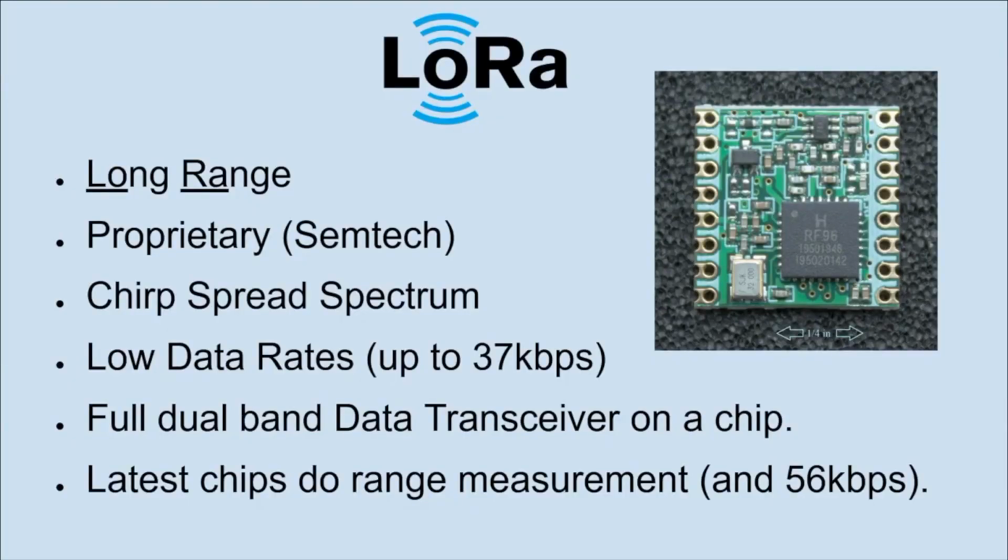We've been using LoRa as a modulation technique for ARHAB for about 5 or 6 years. It's actually grown to the point now where it's coming to be the dominant way that we use for transmission. It stands for long range, and it's a protocol and modulation technique that's been designed primarily aimed at low data rates and long distance. It's sort of the opposite of going faster and faster. It's in fact looking at how far you can get with the transmissions.